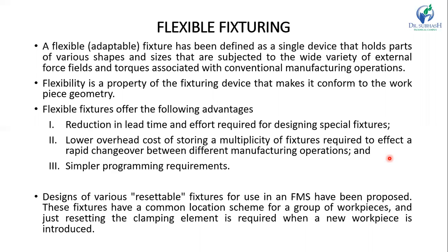A continuous contact fixture is a fixture in which the number of contact points is infinite, such as a line or area contact. So a point contact would completely constrain the motion in a direction normal to the workpiece surface only. So the motions parallel to the workpiece surface would not be completely constrained because of the limited friction in point contact. So surface contact would not only constrain the motion of the workpiece along the three axes, but also would constrain the applied moments.